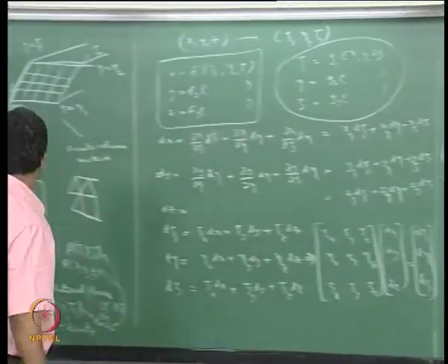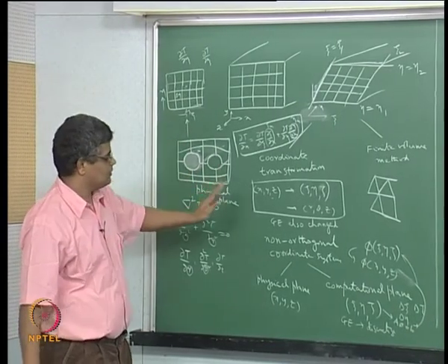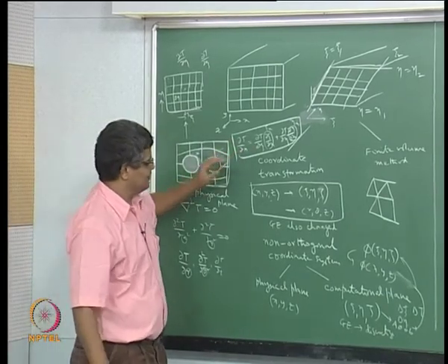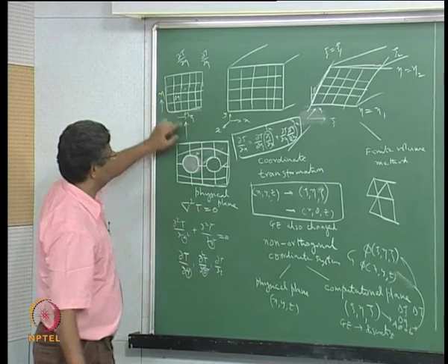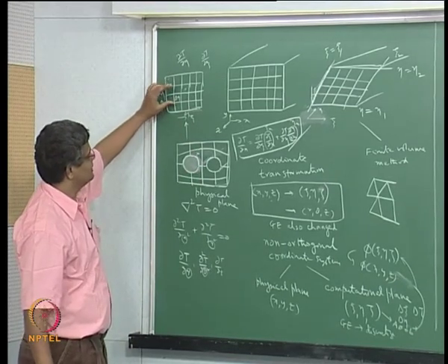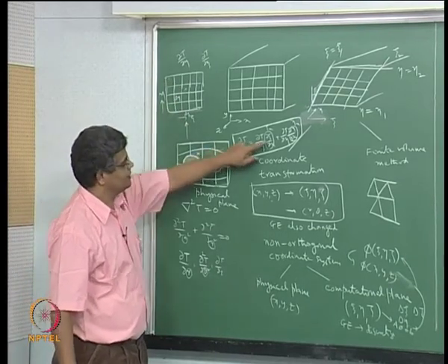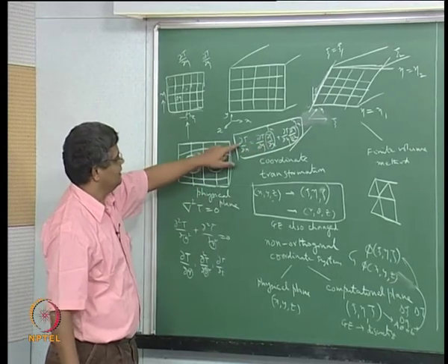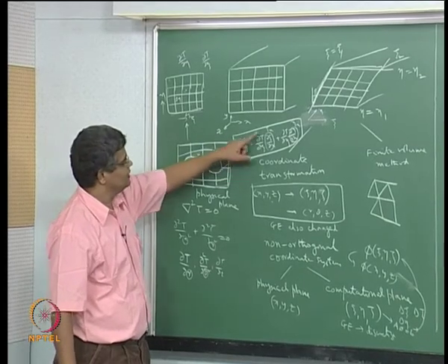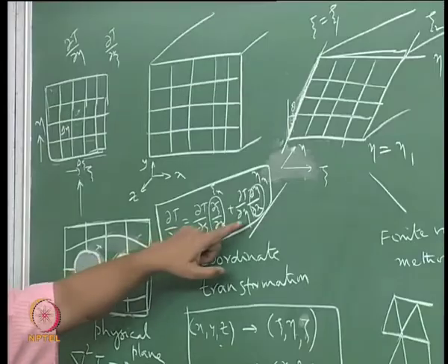And that is how we do the whole computation for this complicated shape. We get a transformation between xyz space and psi eta zeta space, and using this kind of chain rule of differentiation, we convert dou t by dou x, dou t by dou y, dou square t by dou x square, all those derivatives into derivatives in terms of psi eta zeta.